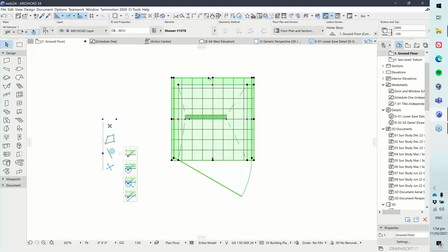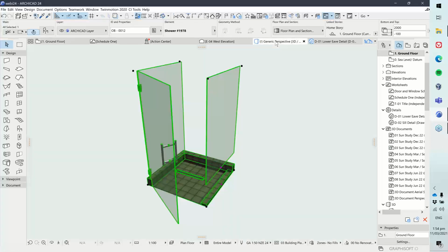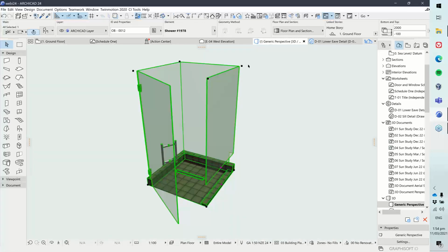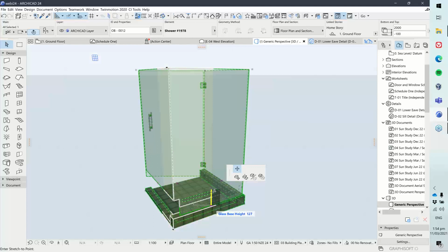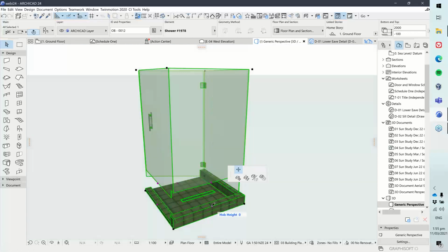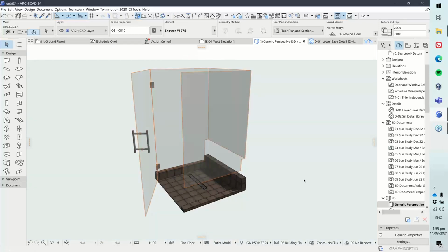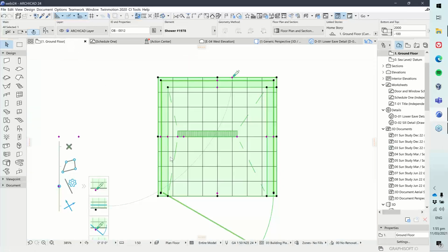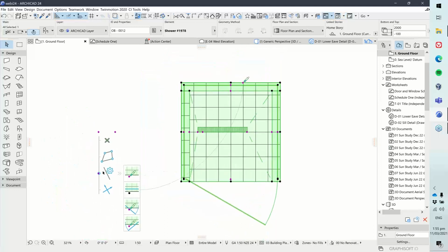So what I want to do is add a piece of glass to the back. So I'm just going to choose this edge type and apply it to this edge. And you can see as soon as I do that, that the glass appears in my floor plan view. And if I jump out to 3D, you'll see that that glass is applied now. And it works the same way that the other glass does. So it has the same settings to let us adjust the base height and the height of the lip. And you can use that to add doors and that sort of thing as well.